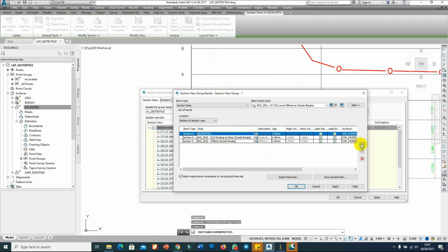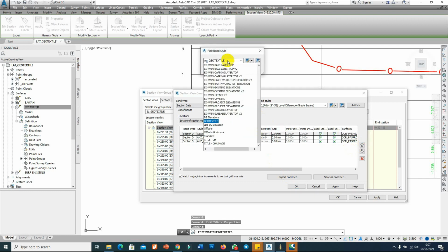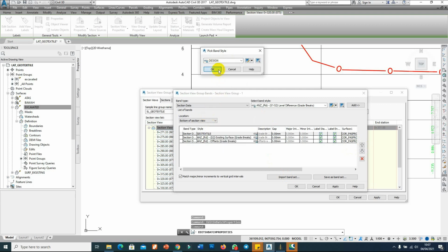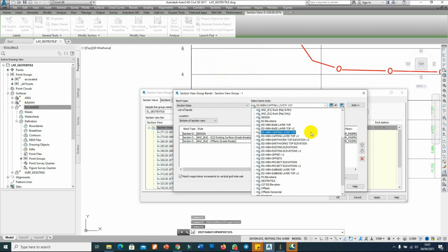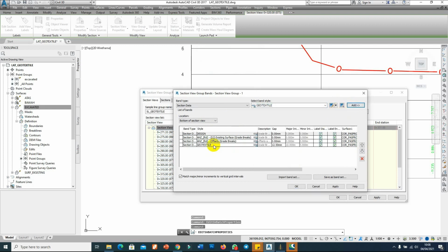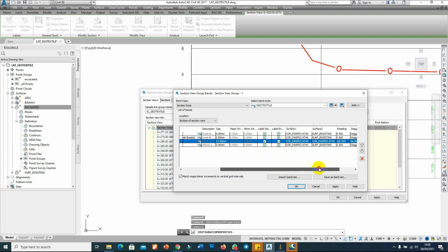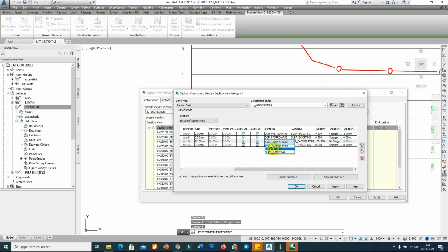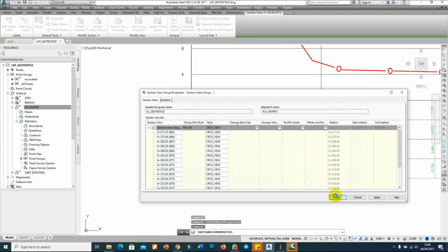Okay. Then I go down. I keep this as the design, still design. Okay. And then I add geotext in here, but I need to push up the offset, so they will be inside in here. Then specifically for the GeoTextile, I need to change to the excavated elevation, and then the gap I put 0. Reading still 0.5. Okay, then okay.